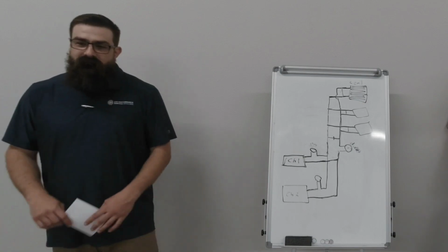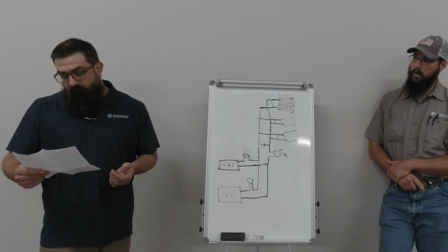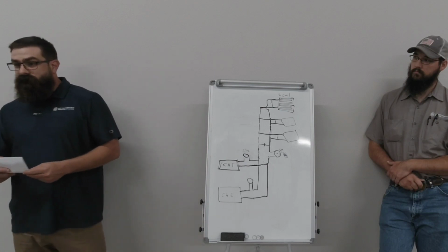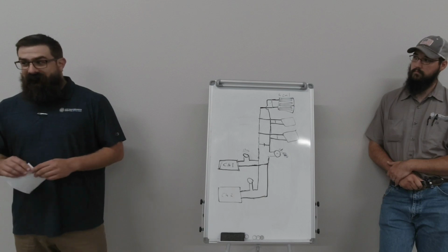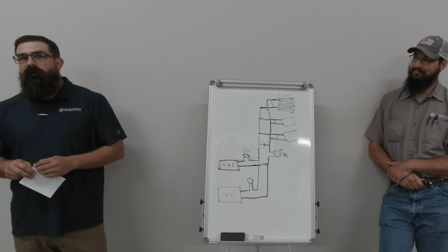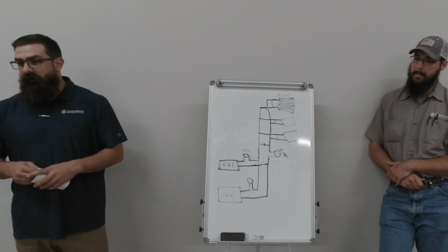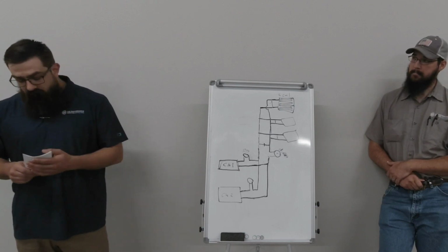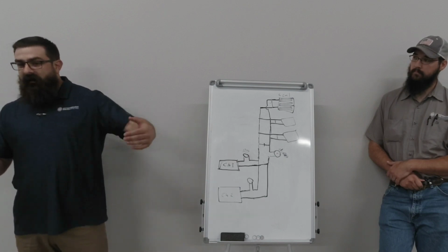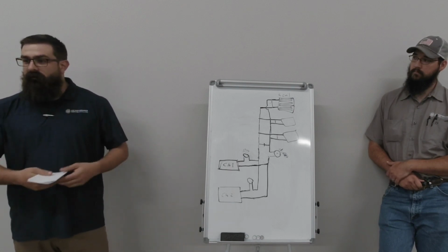No, but who knows? One of the things we didn't bring up in all this would be a heat exchanger. You can have heat exchangers on cold water or hot water, also one on steam, which we won't talk about. A heat exchanger is just another coil. It's just another way to transfer heat or cooling, however you want to look at it. Heat is what they all transfer, but you would pass cold water through it and, through the plate system, draw heat out of another warmer water.